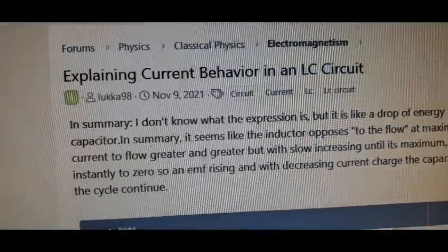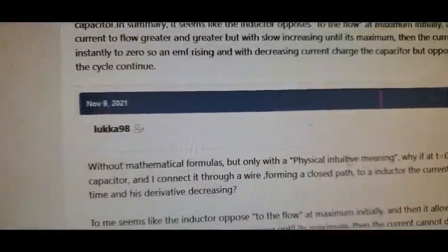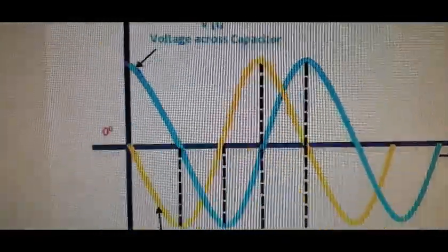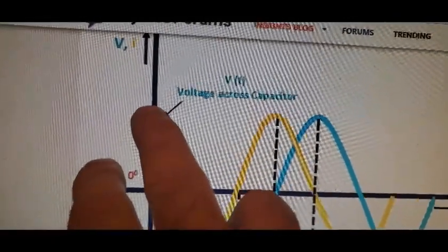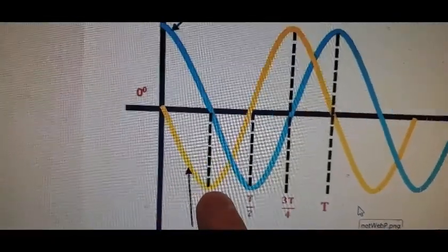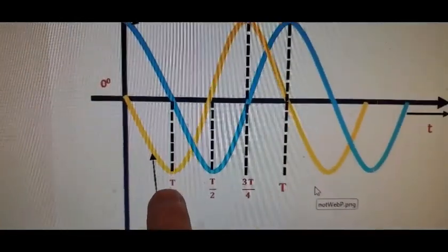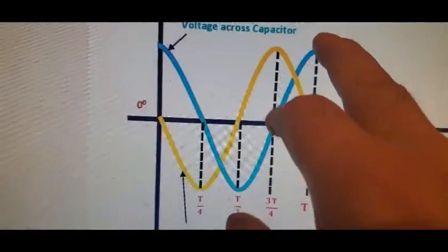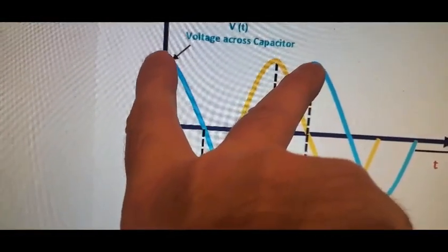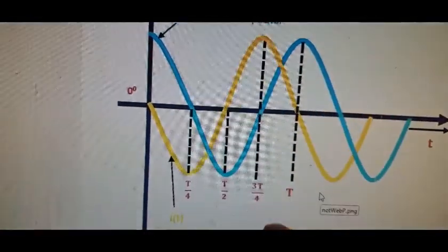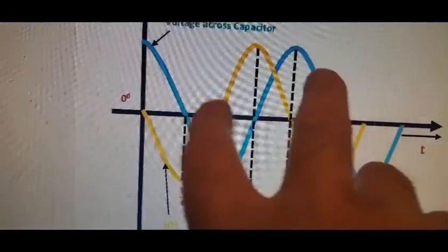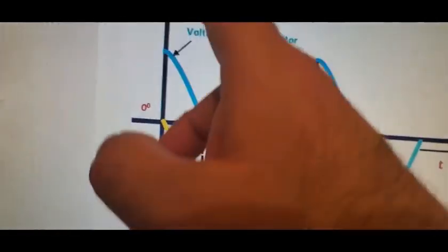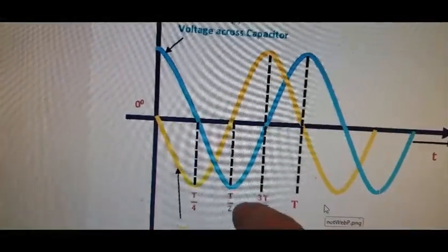And just to reiterate that, this write-up has a nice graph. Here they're talking about the voltage in a capacitor and the amperage in an inductor. Just a few things to get out of the way real quickly. The capacitor discharges, goes negative, goes back to there. That is the time from one wave crest to the other. You put 1 over that time, and that's your frequency, your resonant frequency. You don't have to do anything to it. It just goes at its resonant frequency.